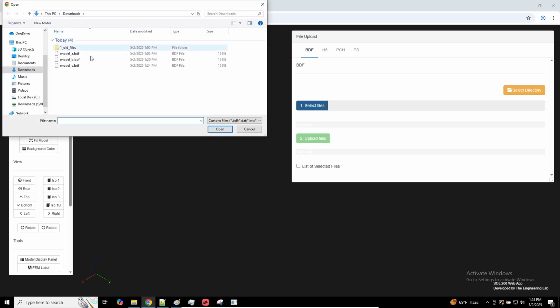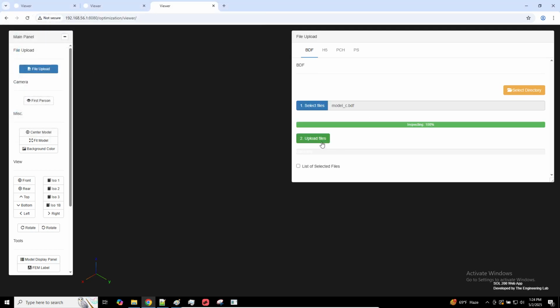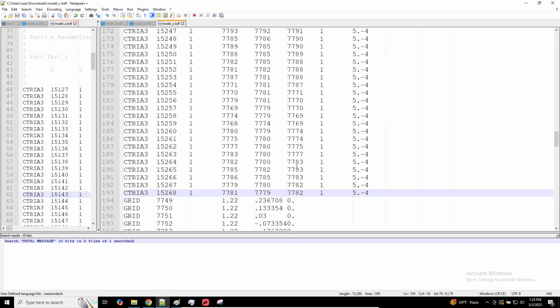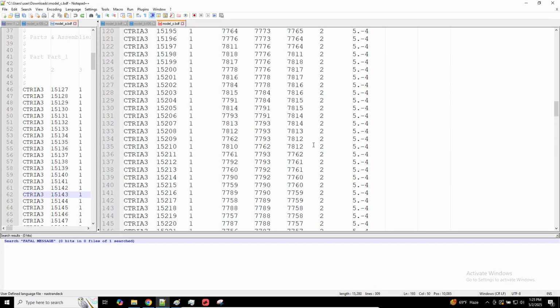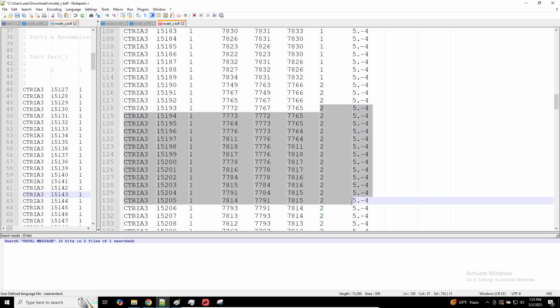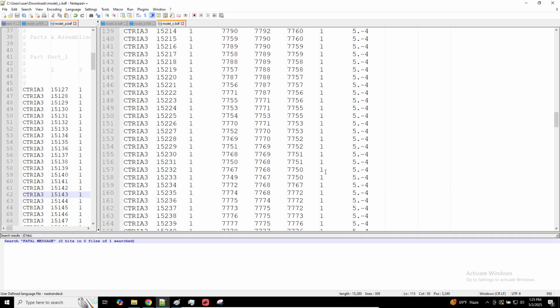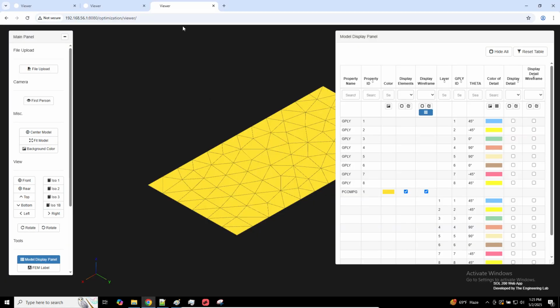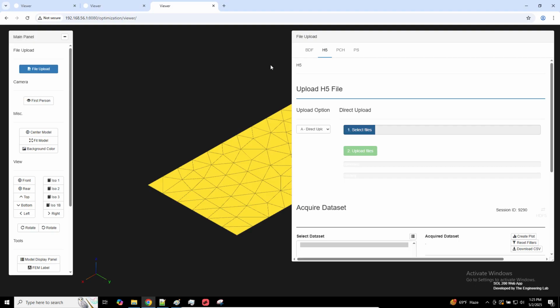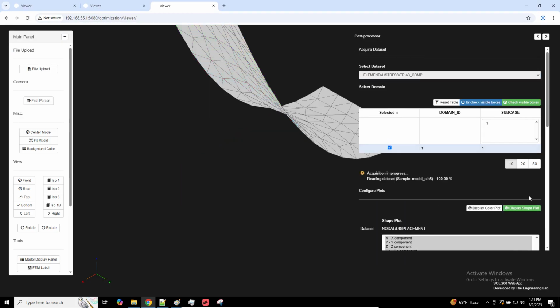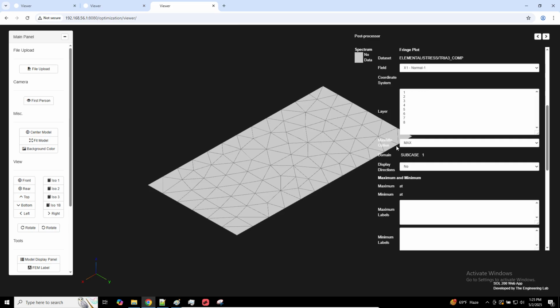Now what I did in that last edit, I said all the elements, all of their material coordinate systems are going to be parallel to only coordinate system 1. So you notice a moment ago, this said 2. So you can see it says 2 here. I said, you know what? Make all of these 1. We ran Nastran, so let's go ahead and upload the results. And now let's look at the results real quick. And we'll do this for layer 3.